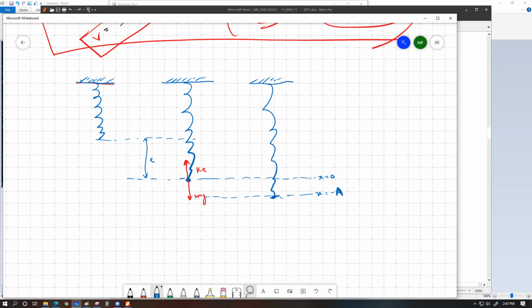So for this position, the force on the particle is going to be an upward force, which is the total pull of the spring, equal to k(e + a), because now the spring is pulled by a distance a further downwards, and the weight always works downwards. mg is still here. So in this case, the resultant force, which is responsible for this motion, for this terminal position, is going to be k(e + a) minus mg.